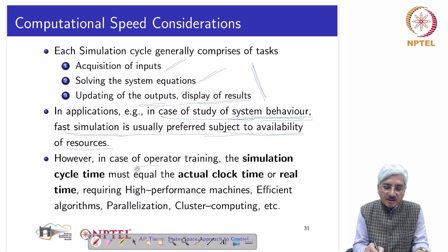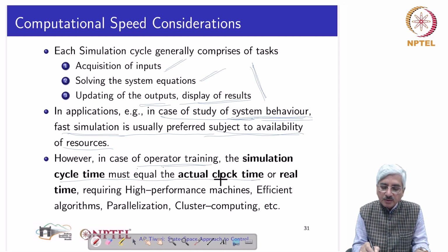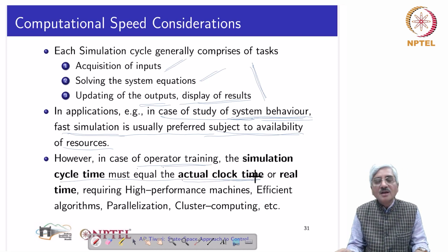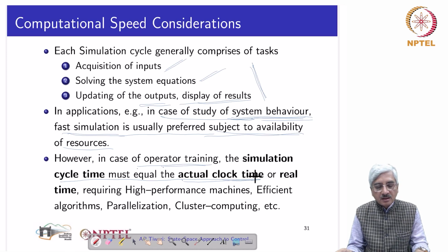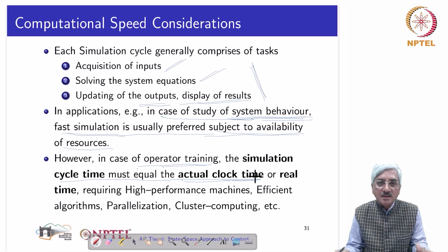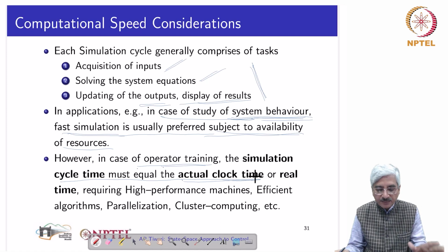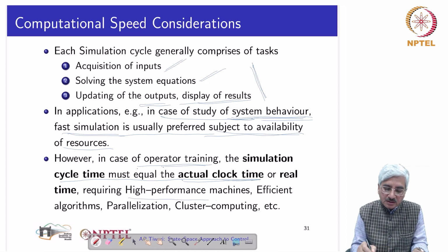However, in case of operator training, the simulation cycle time must equal the actual clock time. Then only the operator will get the feeling of operating a plant. If the system has been represented to its most final details, it may not happen in real time, despite faster computers or high performance machines.